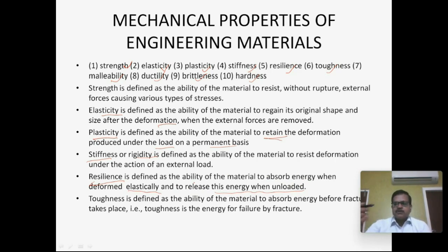So up to the elastic limit, if you are stretching, the member is going to absorb the energy. When you release that load, the energy is dissipated and the member comes back to its original state. So the amount of energy absorbed by the member up to the point of elastic limit is known as resilience.